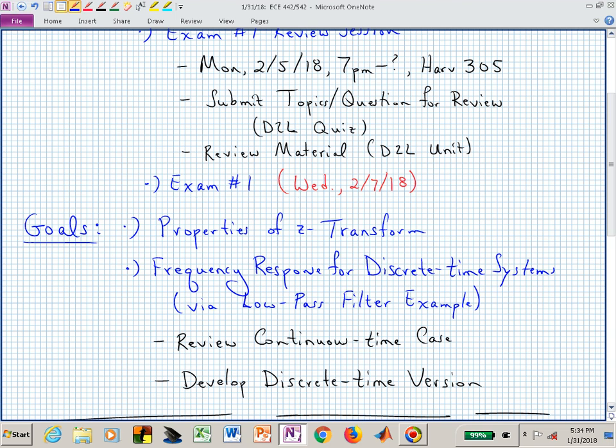We'll change our bandwidth. By the end of the class, hopefully we will have a linear difference equation that will implement a low-pass filter, which means that now you could simply code in that difference equation, put in a string of numbers. Obviously that waveform representing a sequence of numbers would have to be sampled consistent with our sample period, but then out of that difference equation you would be getting this filtered signal response, and that's what we hope to finish with today.